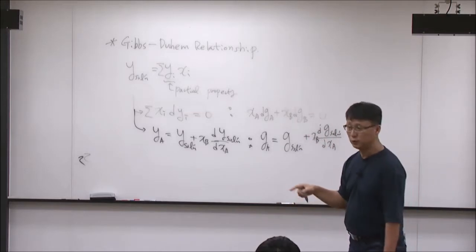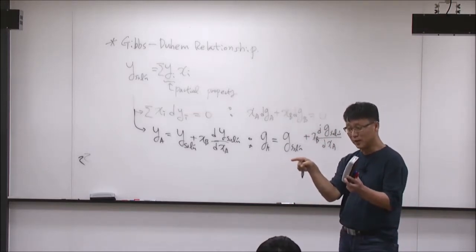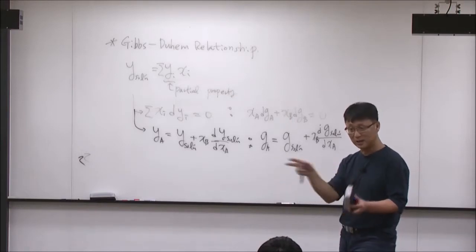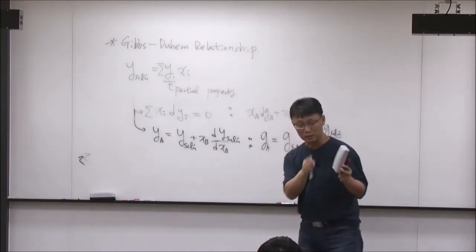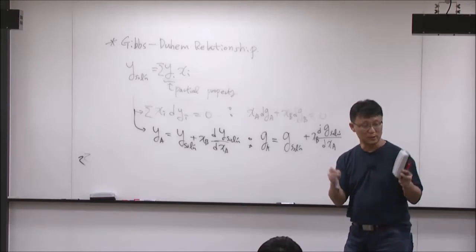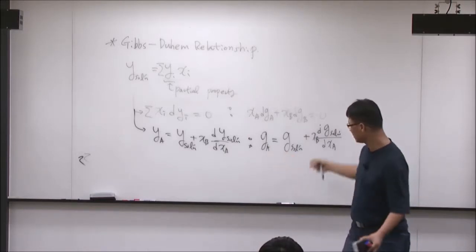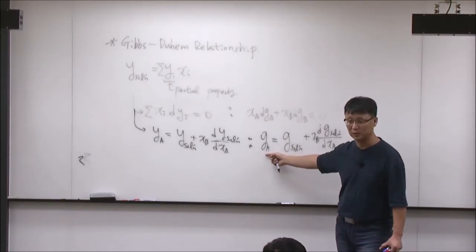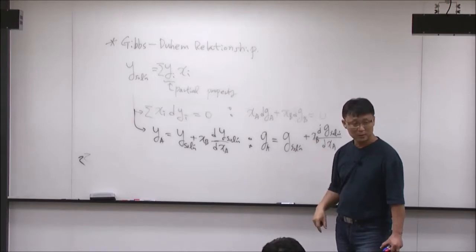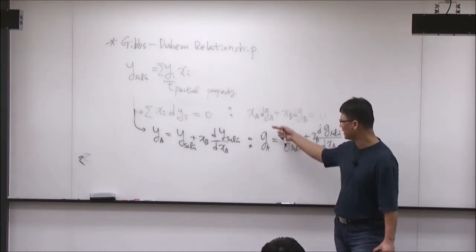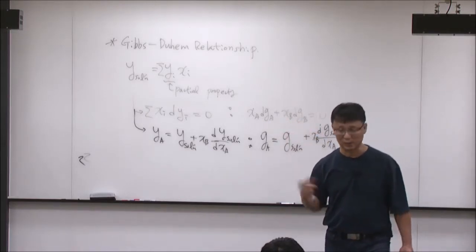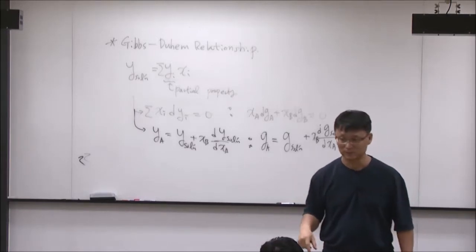People use special equipment to measure the voltage for the given solution. Then they can measure the Gibbs energy of the solution. So when you have an iron-manganese binary system, depending on the composition, you can measure the Gibbs energy of the solution. Then by using this relationship, you can calculate the partial Gibbs energy of A and B. Or if you measure the partial Gibbs energy of one, you can use that to back-calculate the partial Gibbs energy of the other component.